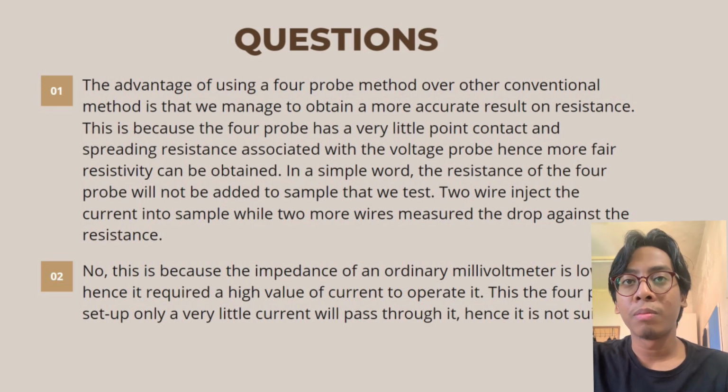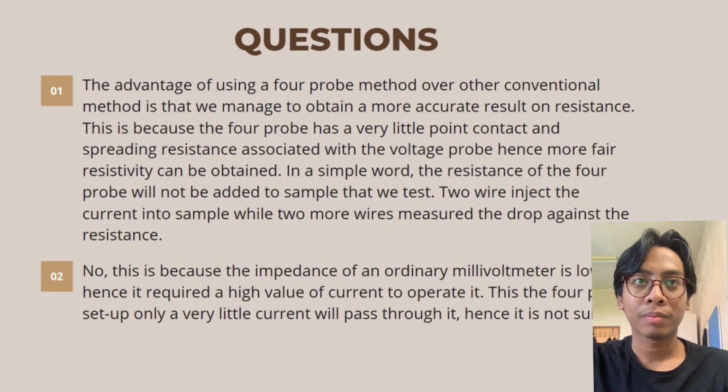To put it more simply, the resistance of the four-probe will not be added to the sample that we test, because two wires inject the current into the sample, while two more wires measure the voltage drop across the resistance.